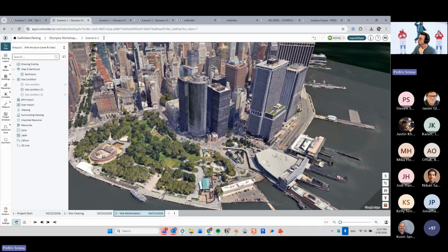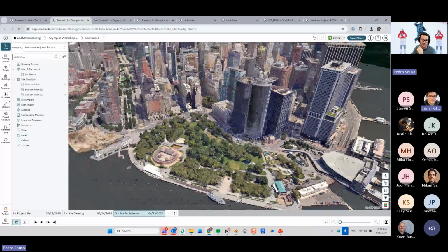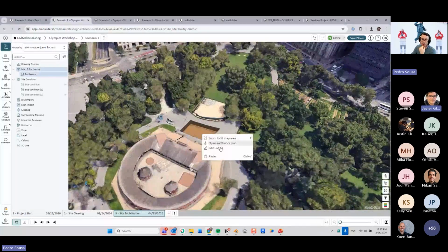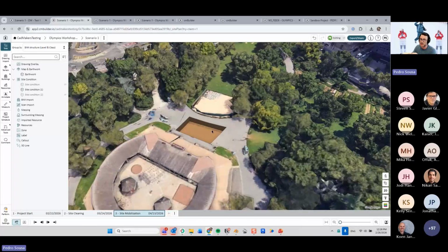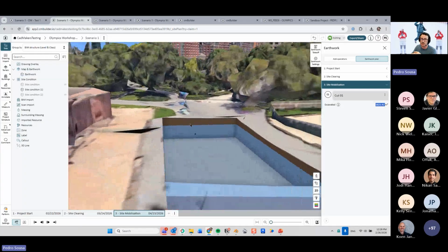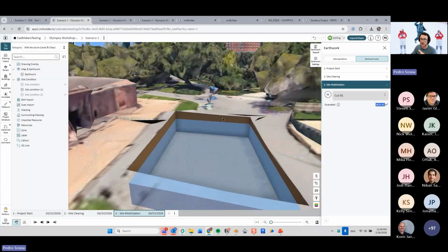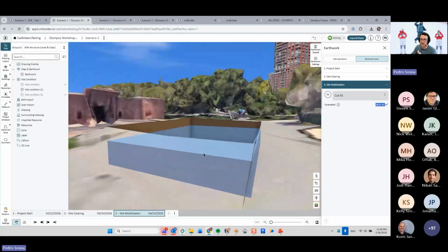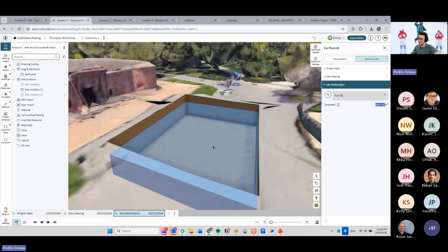Okay. So if you don't flatten out the area and do that excavation, will the volume of mesh be counted as excavation volumes? Excavation volume is always related to the change on the terrain before and after that operation, or the milestones. So when I look at this over here, this excavation volume is related to the total shape that was removed on this terrain. So it will include the new topography all the way down to the cut that you created.